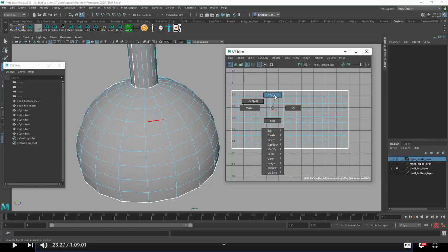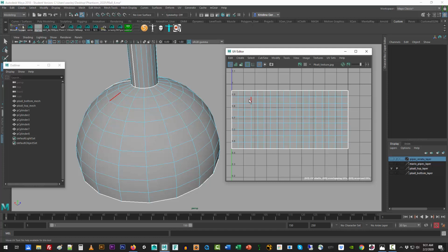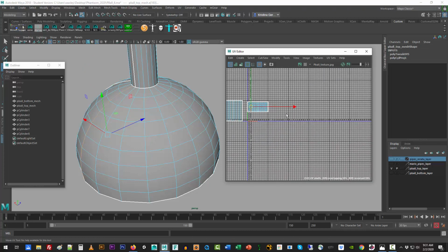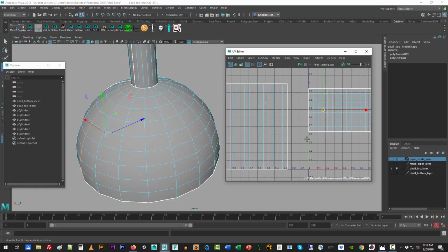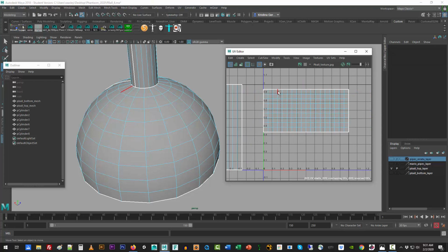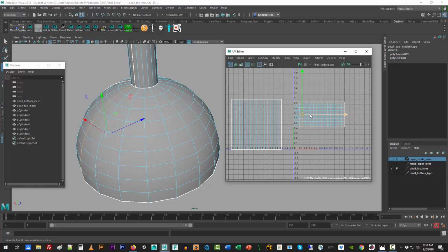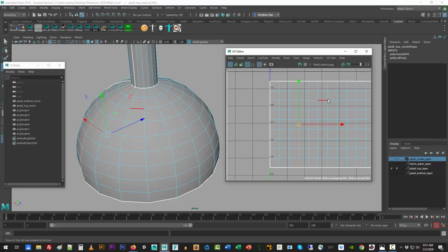The best way to do this is, you can do one of several things to select. You can just select each part by hand, holding down the Shift key. If you have the ability to double click, that's fine. That actually does not select the pipe on the left. And you can, again, verify what you're doing by pressing the F key, and it will show you what you have selected. In this case, it's not including the pipe, so I know that I did not select that side. You can select everything, including the length of the edge, and then just hold down the Control key and deselect, same left mouse click, to get just that clean edge.